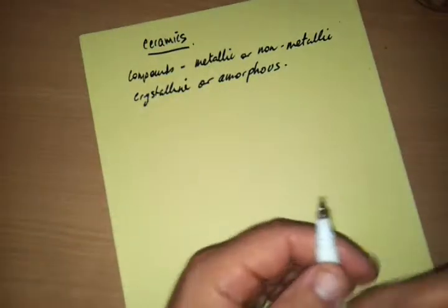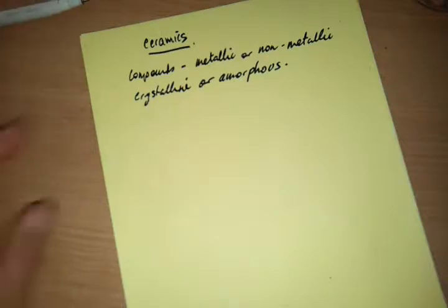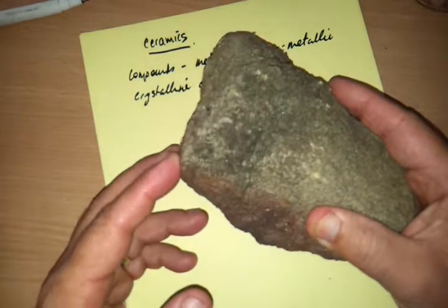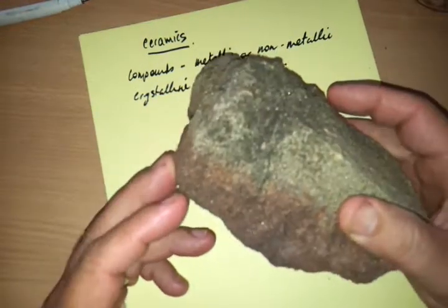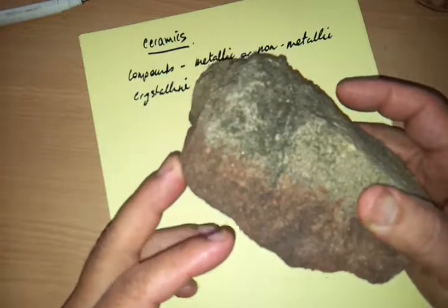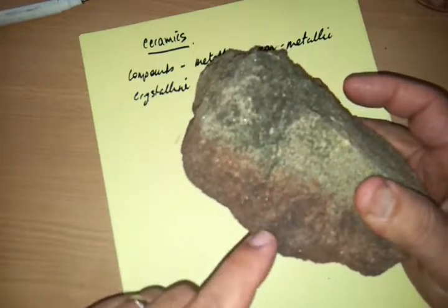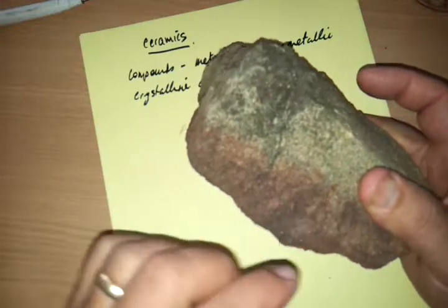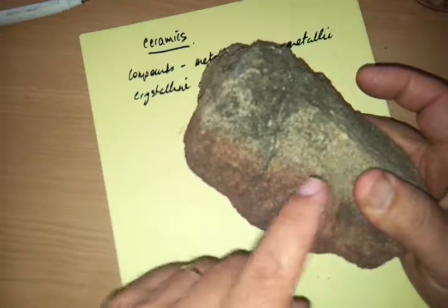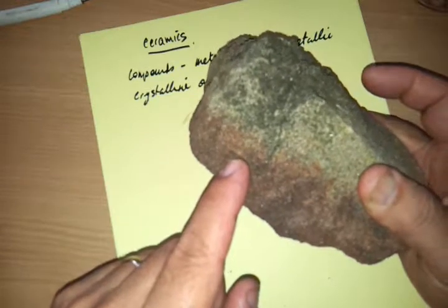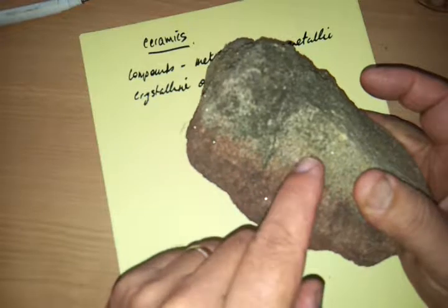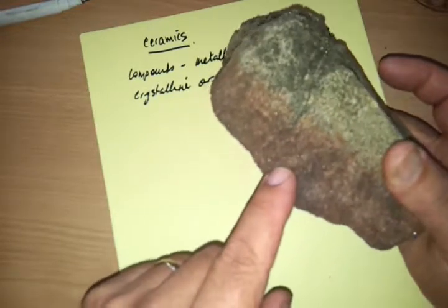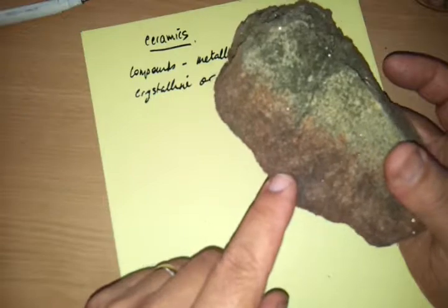Now, naturally occurring ceramics, as I showed you just before, can come in the form of rocks. That's the most popular form. Remember, we're applying all this, the properties and structures, to building materials for civil structures. So this is what's called a sedimentary rock, and it's basically made up of lots of sediments. It's sandstone. Sydney's full of it. And you can see the layers in different colours, and looking in there you can almost probably see some little sparkles going on. Those sparkles are small bits of quartz inside there, together with silicates, sands. The colour comes from metal oxides. Usually the dark red means an iron oxide.